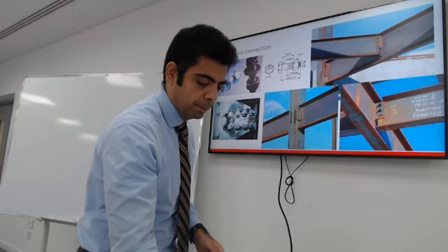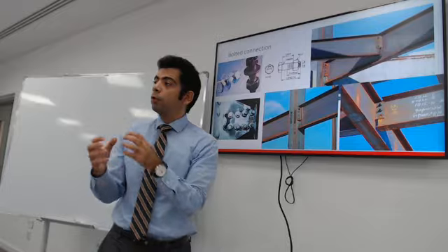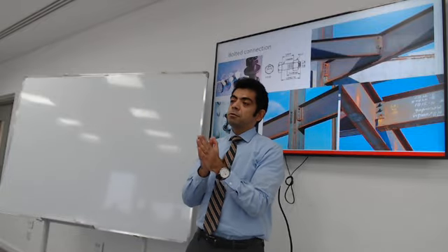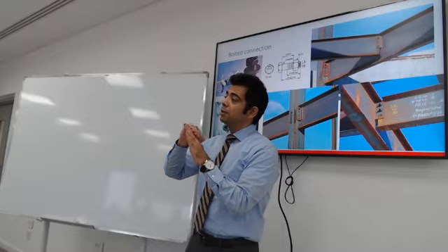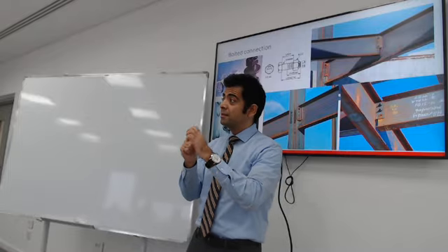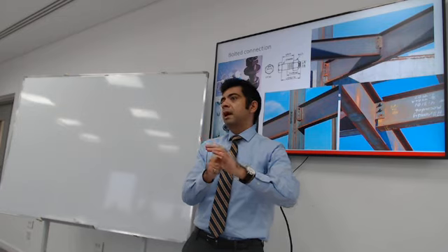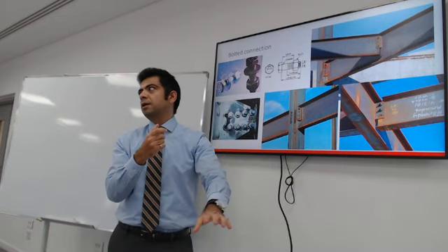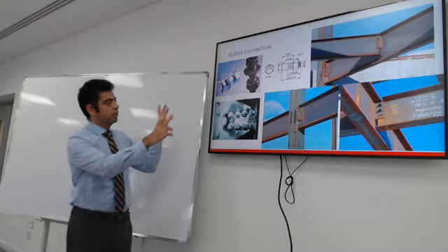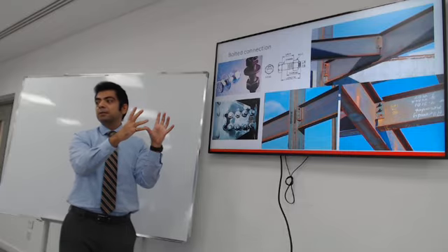So just look closely at how the bolt can fail. Not only is the bolt responsible for the strength of the connection, the material itself could fail. So the bolt could be strong enough, but the steel could reach its limit, and the connection could fail in the steel. This is an example of something called block or group action.